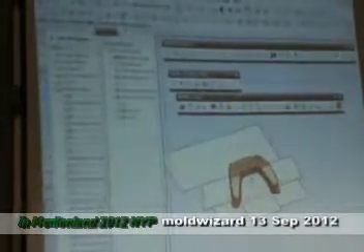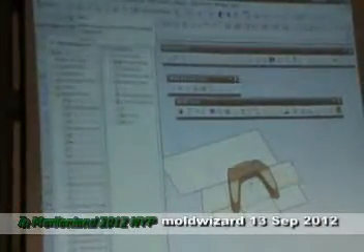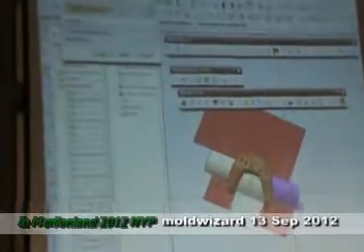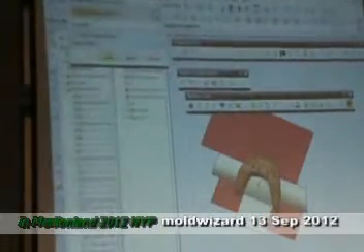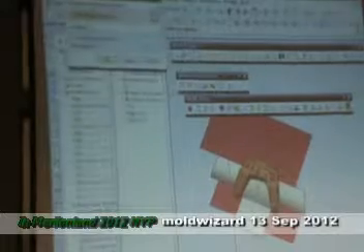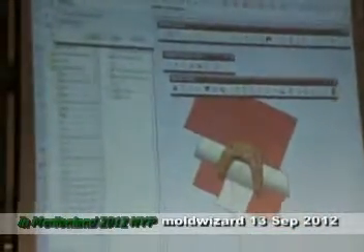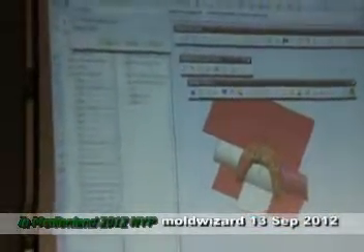I need to save the file first. It's good to save it. Now after that, I will let the system know. These are the parting line. I need to click this. I can click this and tell them these four surfaces are part of the parting line. That's not what I clicked, so that's why it was without.